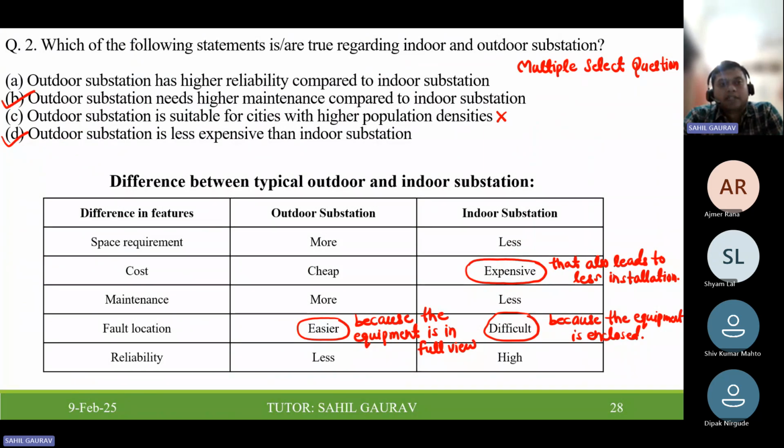The first option says that outdoor substation has high reliability. So it is false. Outdoor substation has low reliability, because it is more prone to faults. B option: outdoor substation needs higher maintenance compared to indoor substation. Yes, it is correct. It requires more maintenance because it is open in the area and more faults can happen.